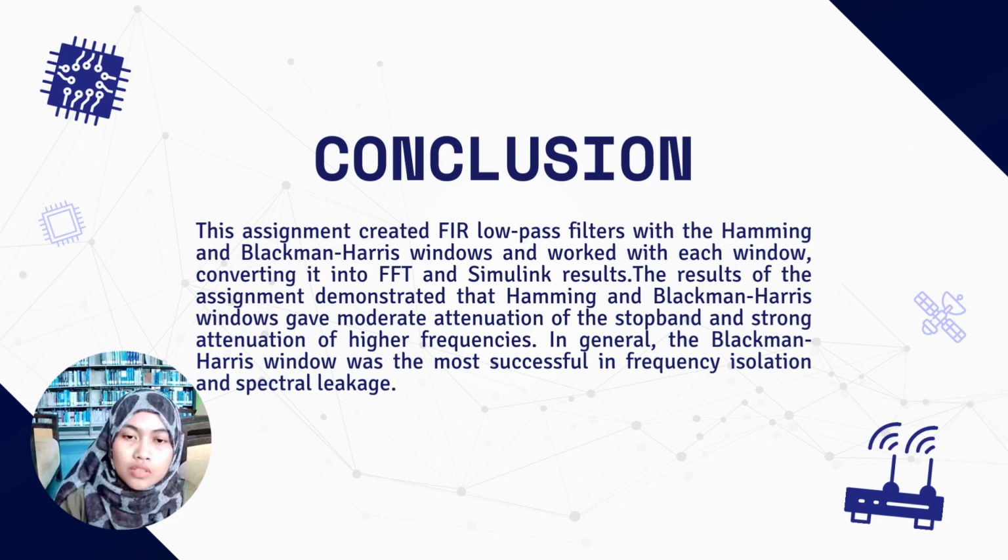Overall, for conclusion, the assignment created an FIR low pass filter with the Hamming and Blackman-Harris windows and worked with each window, converting into FFT and simulating the result. The result of the assignment demonstrates that the Hamming and Blackman-Harris windows give moderate attenuation of the stopband and strong attenuation of higher frequencies. In general, the Blackman-Harris window was the most successful in frequency isolation and spectral leakage.